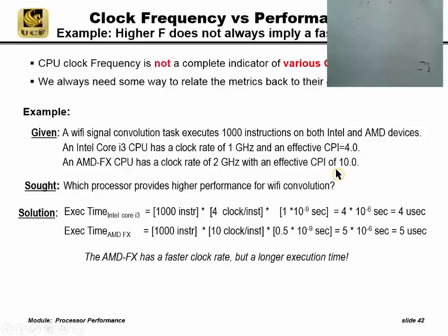You're going to say, well, yeah, this is a very isolated example, and you just change this ratio, and therefore it works this way. But this is very practical. Suppose you're even buying a laptop computer, and you're looking at the clock rate. Getting a faster clock rate may not be as cost effective as adding more cache. Because as we saw, things like load and store operations, which are data transfer instructions, typically have the most clocks per instruction.